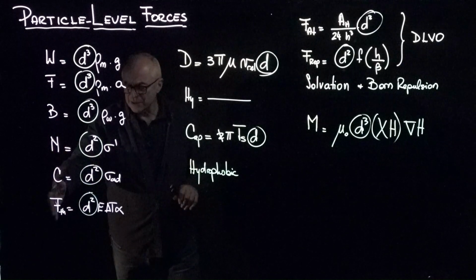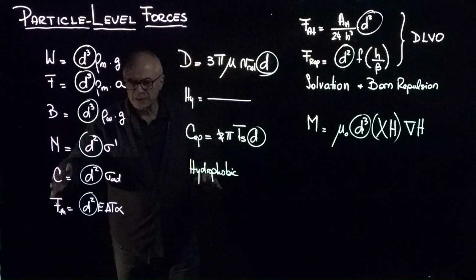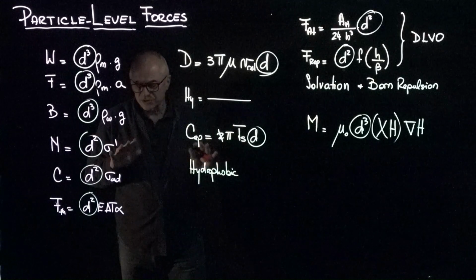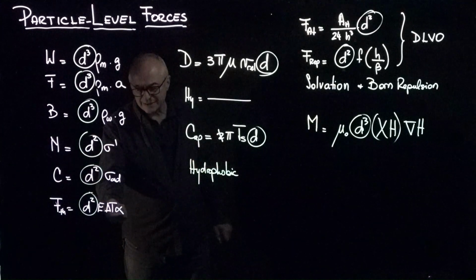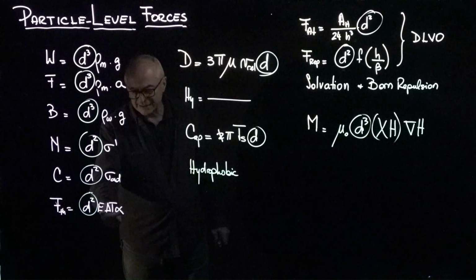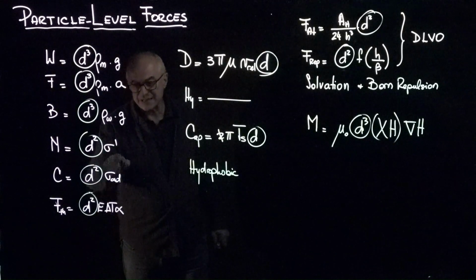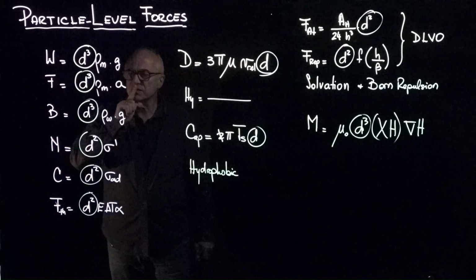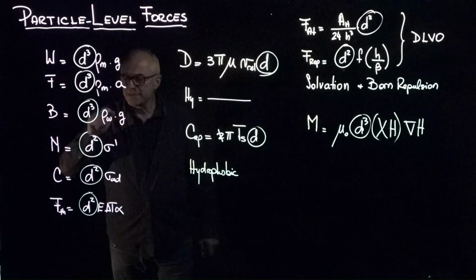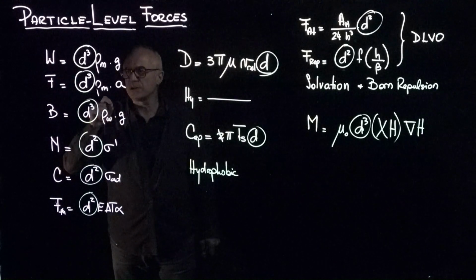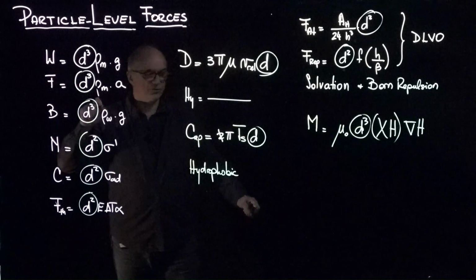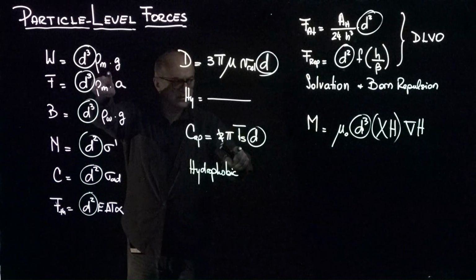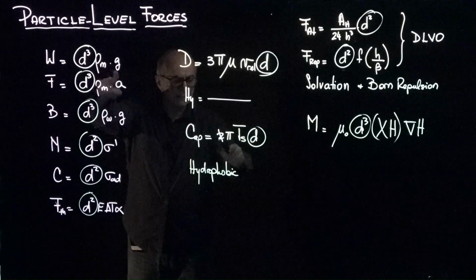That means that thermoelastic effects are going to be important regardless of particle size, and their relevance is going to be determined only by the thermal expansion coefficient and the skeletal stiffness and the temperature change and the effective stress applied. Then we can also see that there may be a certain size for which the capillary force can be more important than even the self-weight. So we'll come back and compute that one.